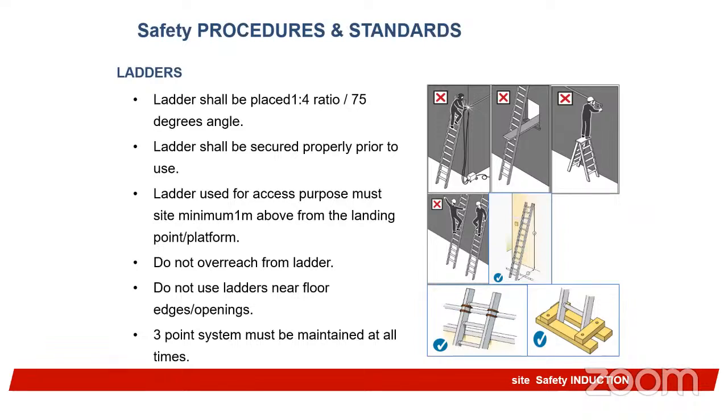Ladders should basically be used for access, but sometimes we use them for some light activities, as long as the ladder has been approved for that purpose, and there must be someone holding your ladder, or you should have something that secures it at the ground floor, and also at the side.